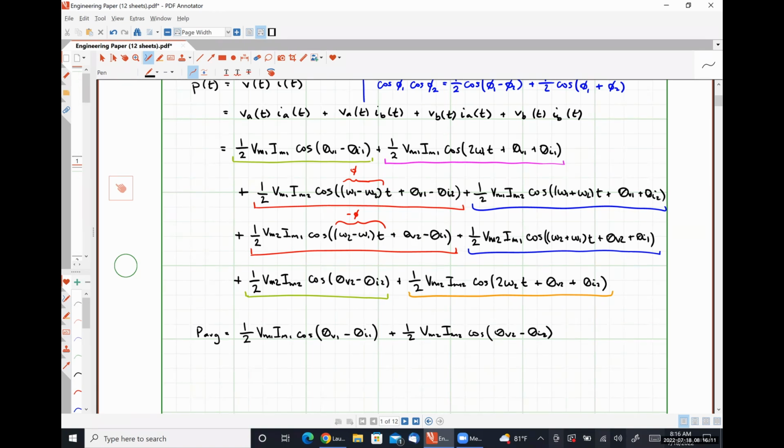And the reason why I say it's incorrectly is because superposition is not supposed to work for power-related quantities, because the superposition principle requires linear calculations, and power is an inherently nonlinear calculation because it depends on the voltage squared or the current squared. In the case of pure sinusoids like this, it winds up working out, but if we had some other type of periodic wave, it likely would not.